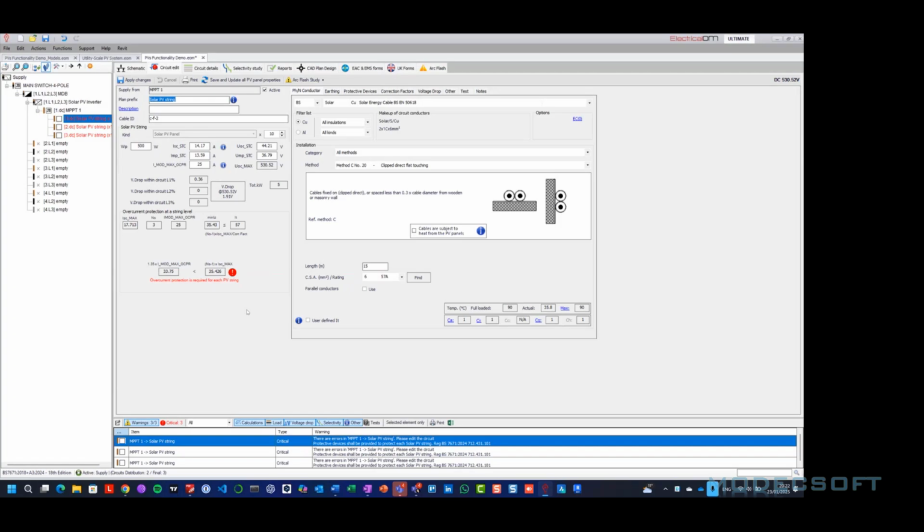And from here, we can see the calculation checks that are taking place in order to help us properly size our PV systems. In particular, because we have 3 parallel PV strings connected together, due to the reverse currents that may occur from any of the other strings, we may exceed the thermal limits of any of these strings, as you can see here. And to check that, we are using the mod max, which is 25 times 1.35. So in this case, this gives us